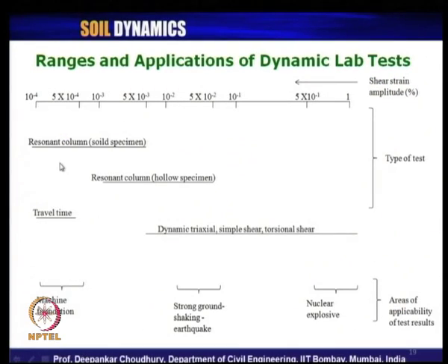So, for machine foundation design, which are the good laboratory tests you can use? Resonant column test, travel time test, bender element test, piezoelectric bender element test, all these values of dynamic soil properties of G and damping ratio you can effectively use for the design of machine foundation. So, only for design of machine foundation this test will be proper.